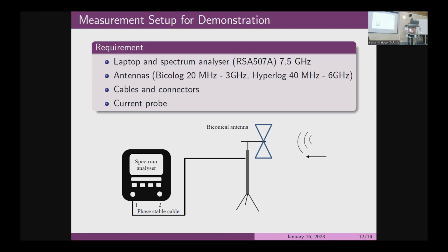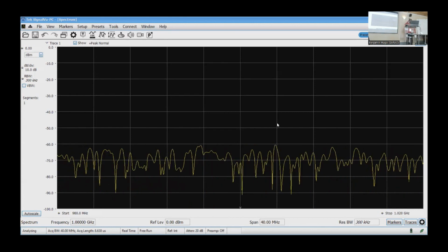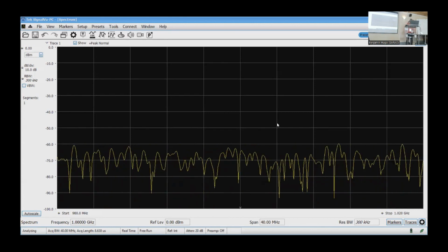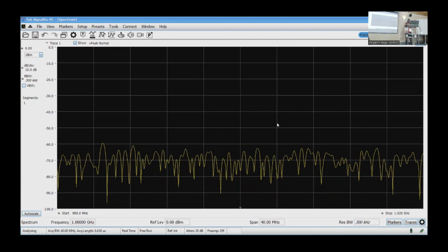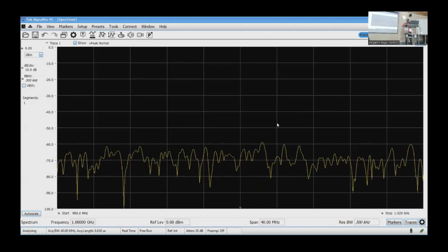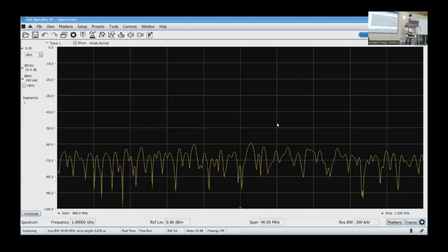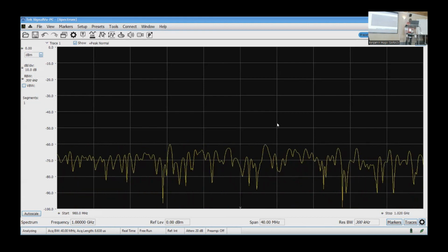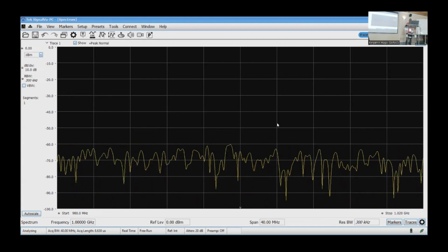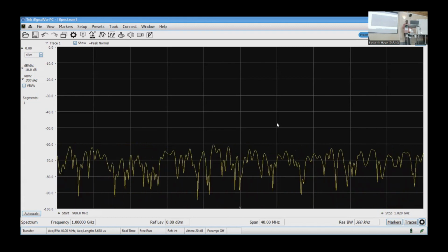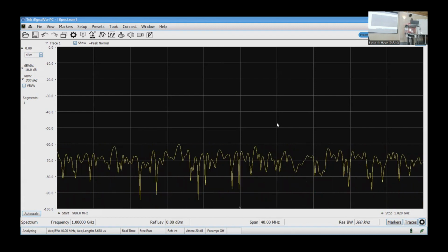And then if you have time, you might do conducted radiations using the current probe that I think operates up to 1 gigahertz. So I'm going to do 2 demonstrations using this. One, we're going to do a demonstration on which band? Bluetooth and LAN are problematic. So we're going to do Bluetooth and LAN because they also share bandwidth, by the way, and that already is a huge problem. And then we're going to do a demonstration on the FM so that you see what we're talking about.